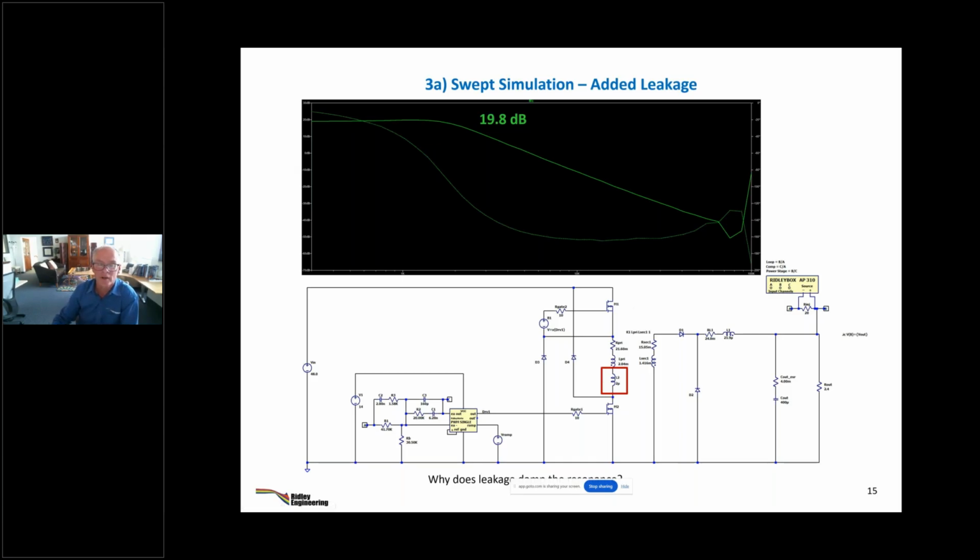By the way, there's a comment there that these switches and diodes, we put these in as ideal elements. You can do what you like, of course. You can put in a real model here for the FET. You'll slow it down maybe a factor of 4 if you do that. The more complex you get with your models, the slower it will run. And any semiconductor companies listening out there, we do not want a transistor device level model of your FET, or of your control chip. We want behavioral models. Otherwise, the simulation is just appalling speed. So there we go.